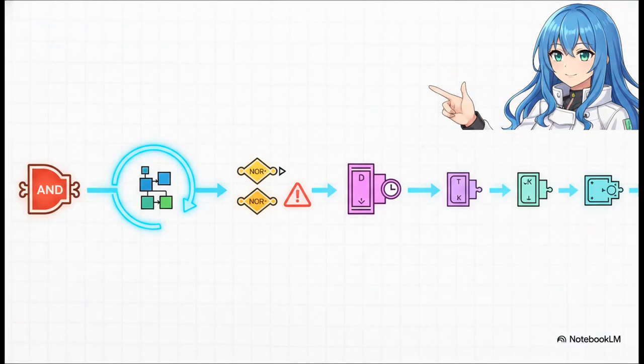So let's just zoom out and recap our journey real quick. We started with a big problem. Simple logic circuits can't remember a thing. The elegant solution? A feedback loop, creating what we call a sequential circuit. Our first try was the latch. It worked, but it had a critical flaw. The big refinement came with the flip-flop, which added a clock for precision timing. And that single innovation sparked an entire family of devices, each one tailored for different digital jobs.